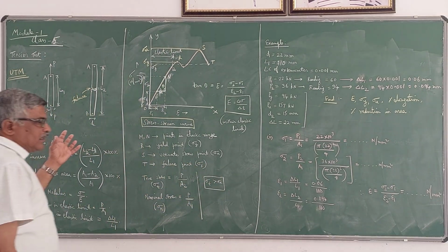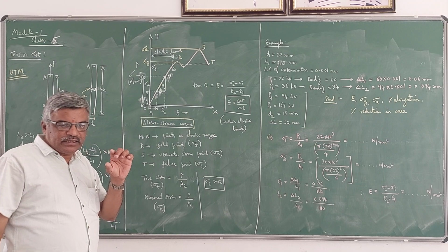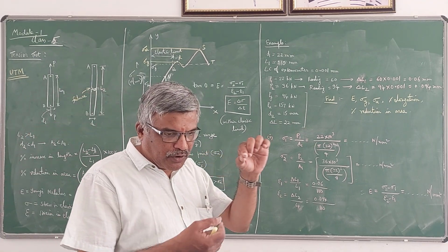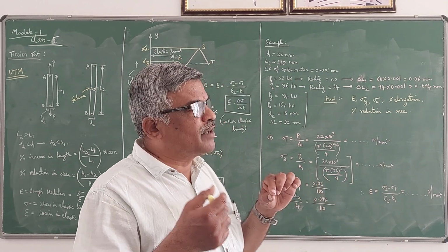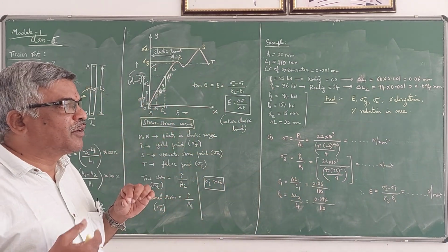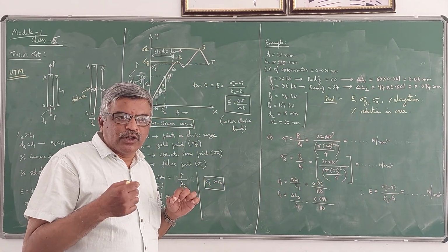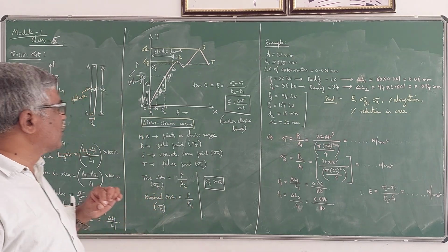So you have to note down two things. One is whatever load you are going to apply, you can start from 0, in terms of newtons, then in terms of kilonewtons. Till the failure of the specimen occurs, you have to slowly, gradually apply the load.